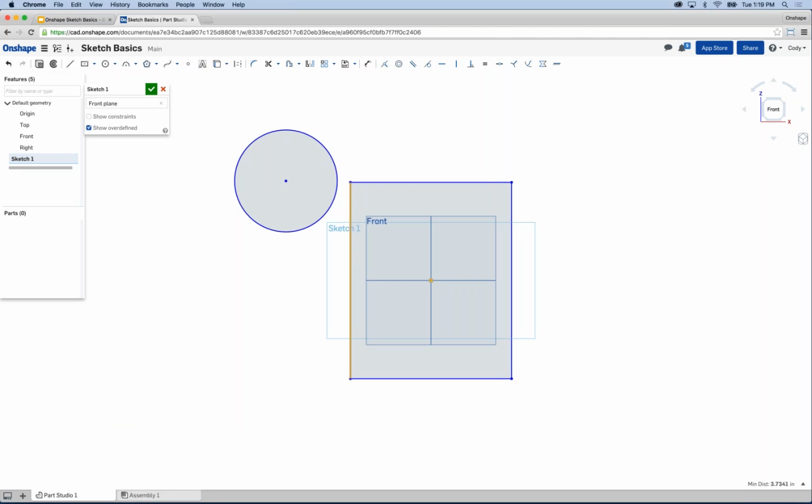And again, if you've come from a traditional CAD system, that's a very familiar thing. I think that's a standard in many different CAD systems. But again, right to left will automatically select anything touching the window selection you've made. And left to right will select only what's fully encompassed within that selection. Okay. All right, so let's move on.